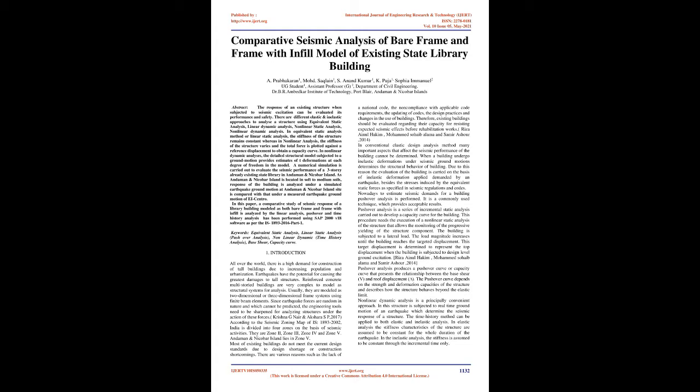Abstract: The response of an existing structure when subjected to seismic excitation can be evaluated for its performance and safety. There are different elastic and inelastic approaches to analyze a structure: equivalent static analysis, linear dynamic analysis, nonlinear static analysis, and nonlinear dynamic analysis. In equivalent static analysis, or linear static analysis, the stiffness of the structure remains constant, whereas in nonlinear analysis, the stiffness varies and the total force is plotted against a reference displacement to obtain a capacity curve.